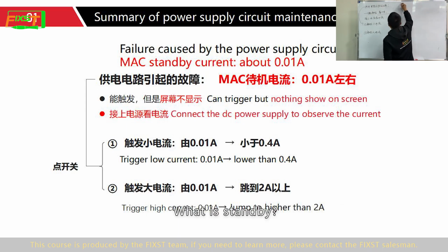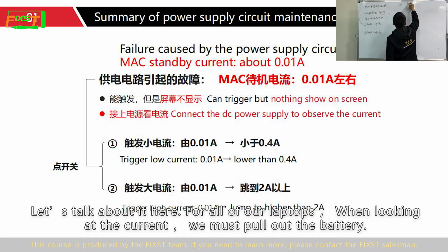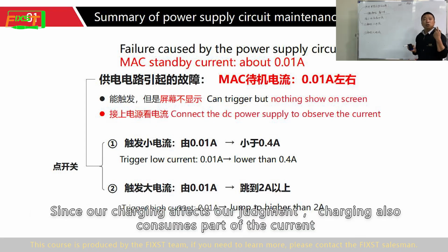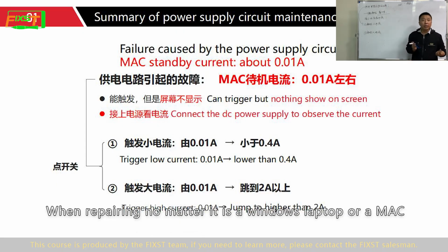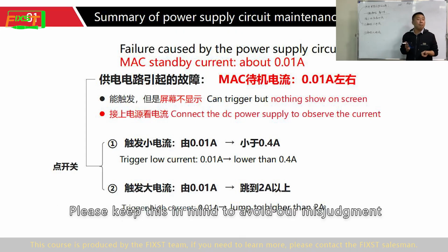What is standby? It's the current state before we press the switch. Let's talk about it here. For all of our laptops, when looking at the current, we must pull out the battery. Why? Since charging affects our judgment, charging also consumes part of the current. When repairing, no matter whether it is a Windows laptop or a Mac, when looking at the current, be sure to take down the battery. Please keep this in mind to avoid misjudgment.